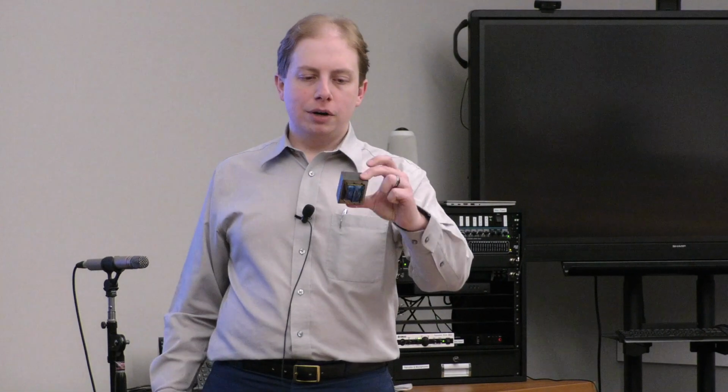Right. So within certain voltage limits, again, you can't exceed the voltage that would cause this to arc over. But it doesn't really matter how much voltage you put into one side, you'll get 1/10 or 10 times, depending on which direction you use it. And the voltage source is connected to the primary coil, and then the secondary coil goes to the load. Again, that's more of a mnemonic in the product. So this transformer right here doesn't care which side is the primary and which side is the secondary. It'll transform up or down depending on how you connect it.